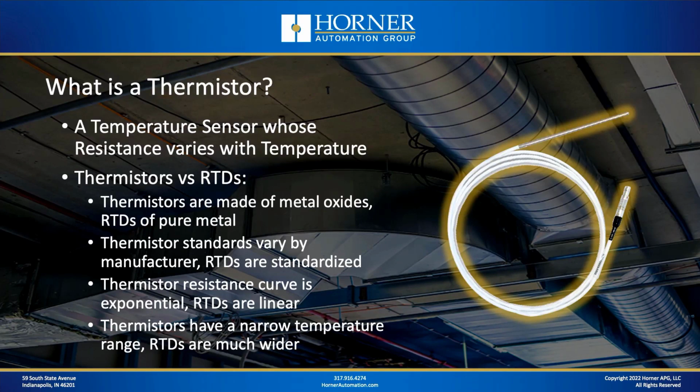Another thing about thermistors is their resistance versus temperature curve is exponential, whereas RTDs are much more linear. Also, thermistors have a narrow temperature range, whereas RTDs have a much wider range. And if we add thermocouples into the mix, thermocouples have the widest range yet. Okay, so those are some differences between thermistors and RTDs, both sensors whose resistance varies with temperature.